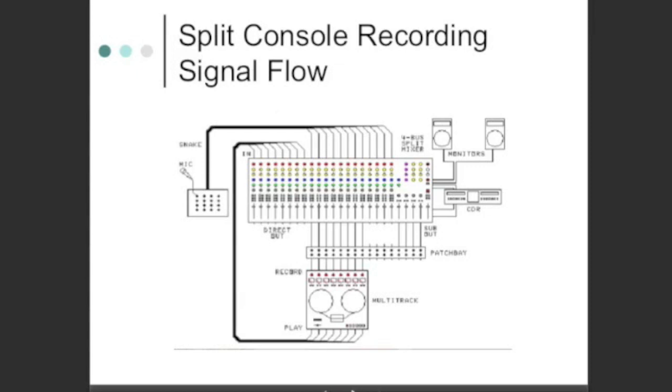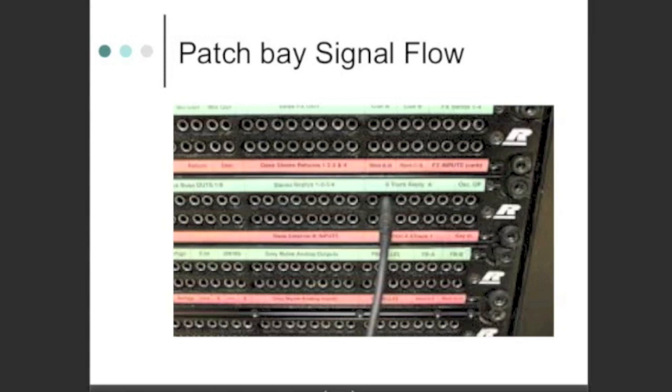Of course, in a recording studio, you've got a major amount of gear, and so instead of crawling behind the pieces of gear when you want to change the signal flow, what they do is they take the inputs and the outputs and put them on what's called a signal flow patch bay. Every path that you see in the block diagram is broken in its path and fed to patch points where you can access all of the paths and rearrange them if you choose to.